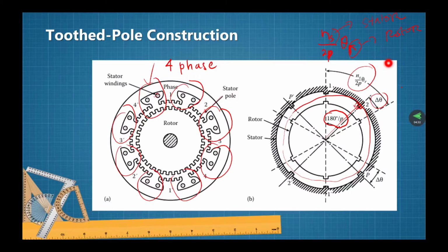In full stepping, after P number of switchings or steps, where P is the number of phases, the adjacent rotor tooth will take the previous position of the particular rotor tooth. And it follows that the rotor rotates through theta r, or the tooth pitch of the rotor, in P steps.